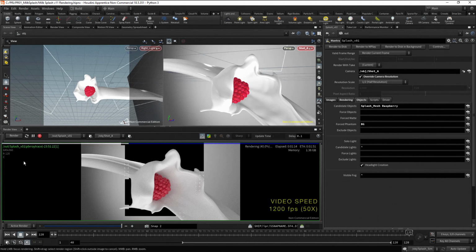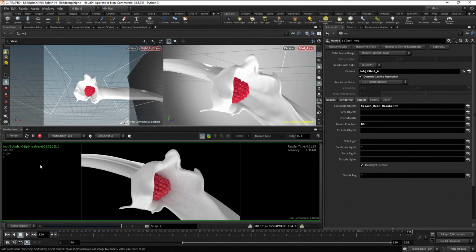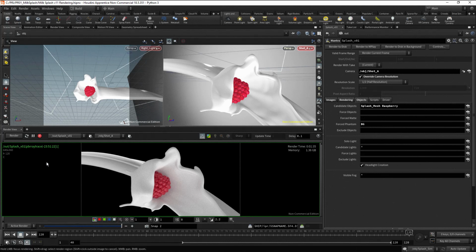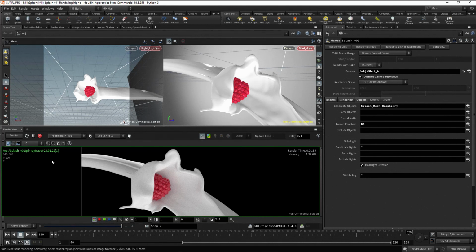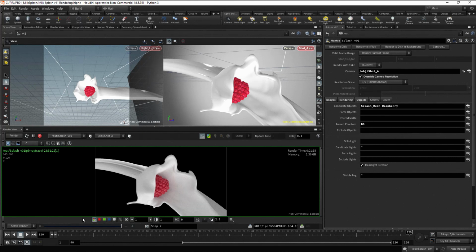The background is gone. Right-click on the render view and select Color Correction. Right-click again and select the View Bar option. In the View Bar, press the Fit to Viewport button to frame the rendered image. Now, in the Color Correction toolbar, you can see, besides our color information, we have alpha information. Display the color information and save a snapshot.